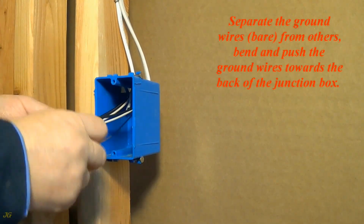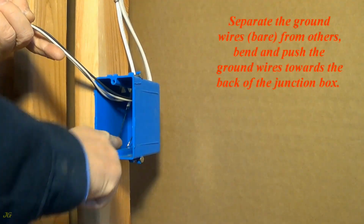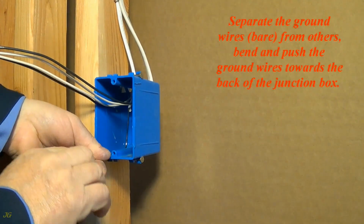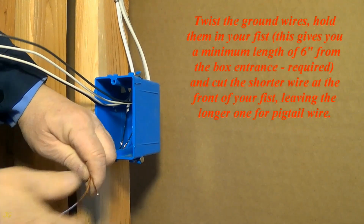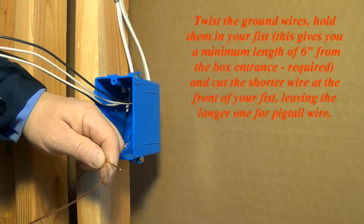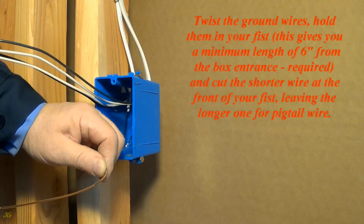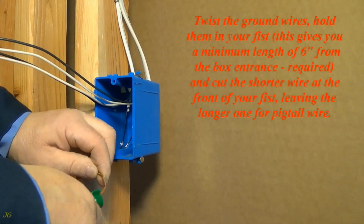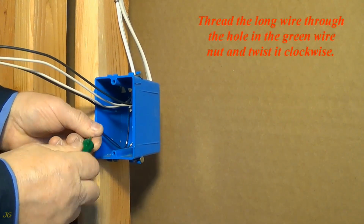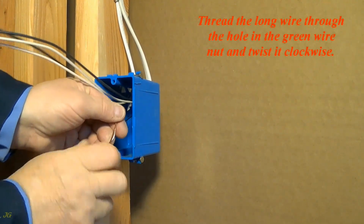Separate the bare ground wires from the others. Bend and push the ground wires towards the back of the junction box. Twist the ground wires and hold them in your fist. This gives you the required minimum length of 6 inches from the box entrance. Cut the shorter wire at the front of your fist, leaving the longer one for the pigtail wire. Thread the long wire through the hole in the green wire nut and twist it clockwise.